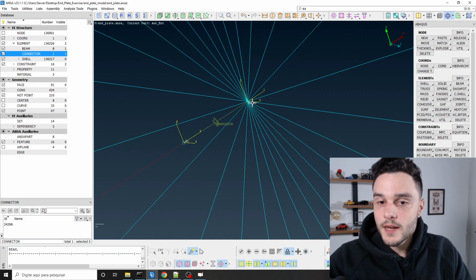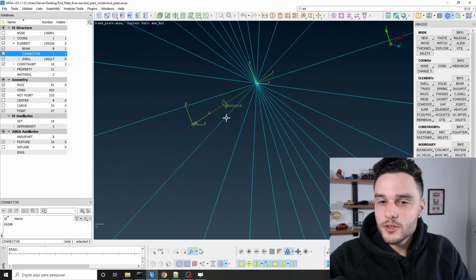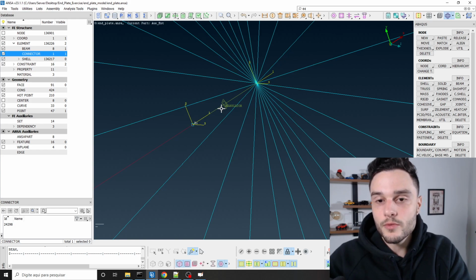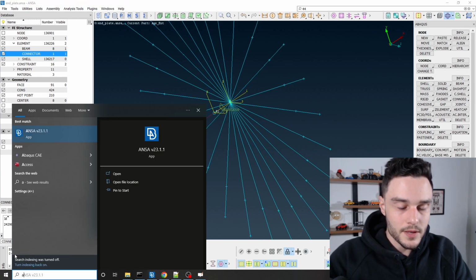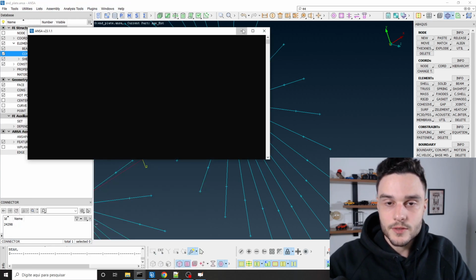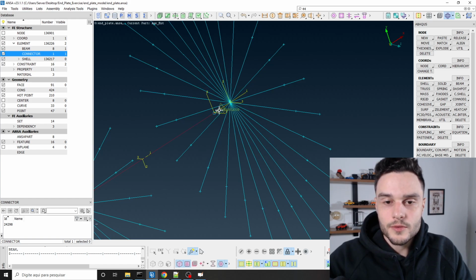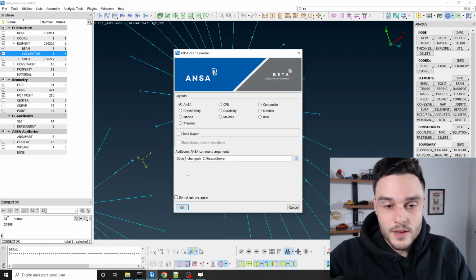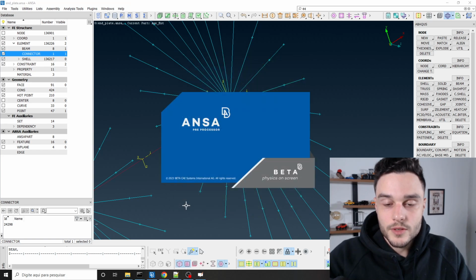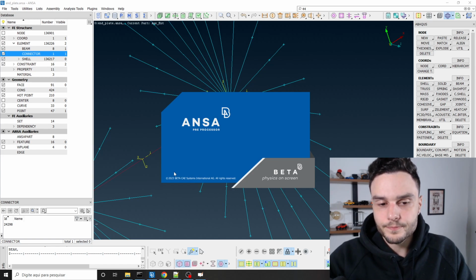Okay, and in here, it's not so simple to explain why we need to use a translator that allows only movement in the x1 direction, but when we get to model the nut and bolt using solid elements, it's easier to understand why we need to use a translator connector. Let me open this model and I'm going to explain this to you right now.